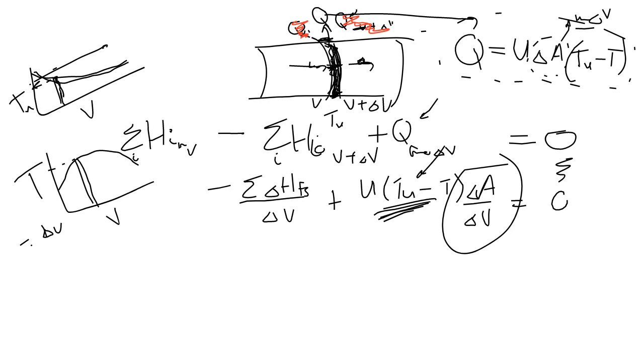So this delta A over delta V becomes that small little a, because for our tube, that is a constant. The area available per volume, we calculated using the circumference times the delta Z. And the volume I can calculate as the cross-sectional area times the delta Z. So this ends up, please go and revise that, as being equal to 4 over the diameter of my tube.